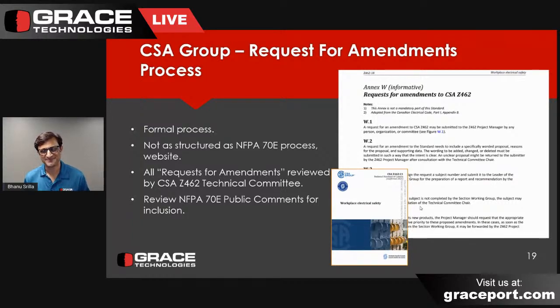So we just don't have the software tool for CSA group, but I really want to encourage everybody on both sides of the border. If there are Canadian listeners today, which there are, we need your comments. We had 0 comments on every edition of Z462 in Canada, and that's sad. The users need to know that you can influence, but you have to submit comments. You have to ask for technical clarification as well directly from Z462, which is very important in this current edition with respect to the inclusion of 240-volt single phase as sustaining an arcing fault, which I'll get to later.